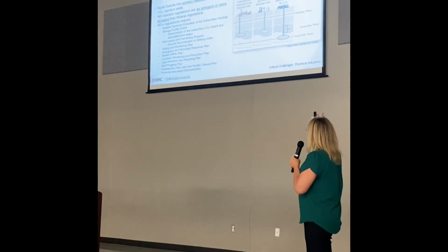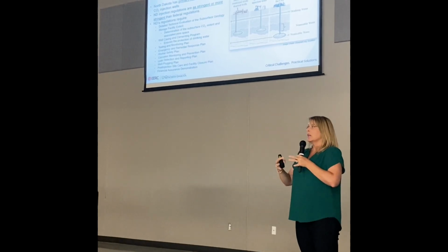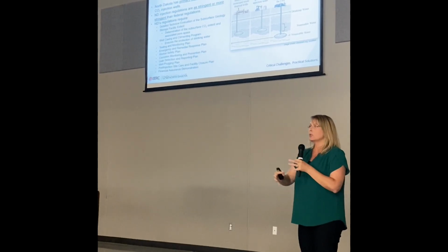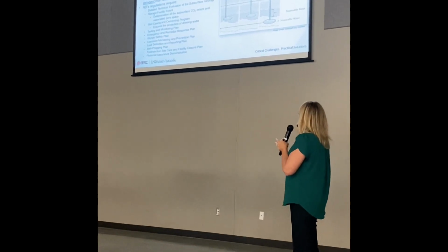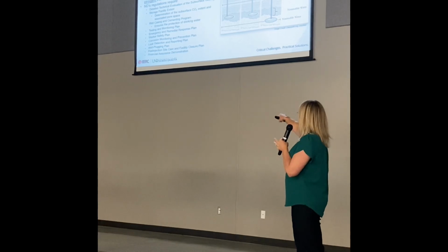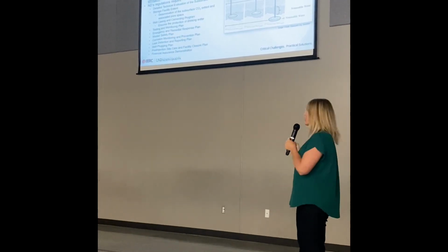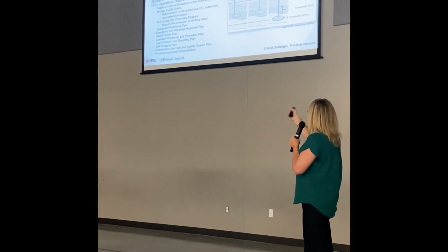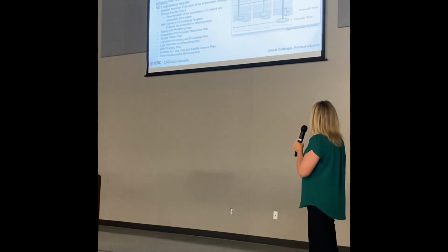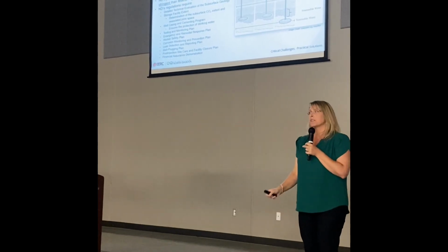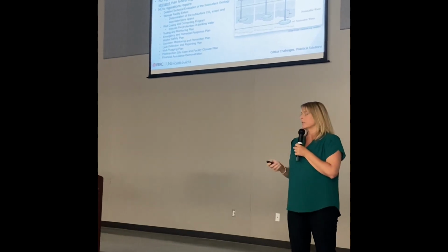You have to do a detailed evaluation of the subsurface geology. You have to estimate where you think the CO2 plume extent will be in the affected pore space. You have to ensure that the well casing and cementing, everything, is solid, and you have all the necessary protections in place. You need a testing and monitoring plan and an emergency remedial response plan, and you can see it all. It's very rigorous, this process for getting a CO2 storage facility permit approved.